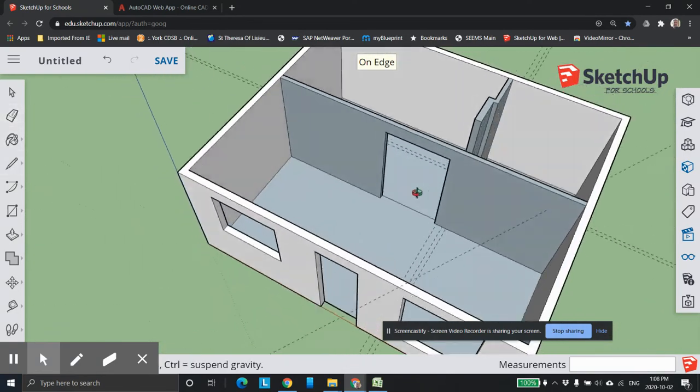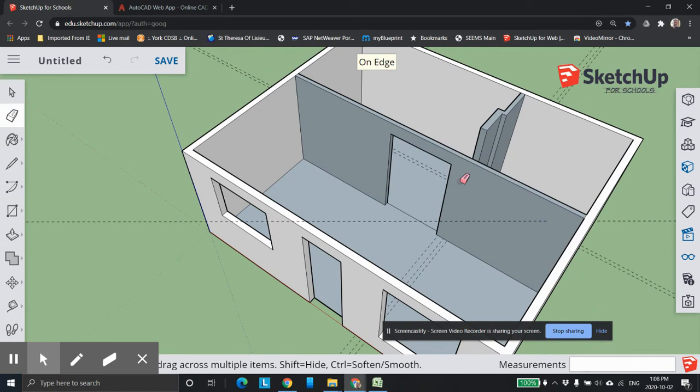All right, so that's the next step. So this video here, recap, you're using AutoCAD to get the dimensions. As I stated, you can bring the image in, but I think this is a much cleaner way to do it. Use the AutoCAD, tab back and forth between the two, draw your exterior walls, make them the proper thickness, which is usually 6 inches thick. Then you bring your interior walls in, lay out all your interior walls, and then we'll cut all of our windows. And then the next video, we'll start bringing stuff in. We'll maybe add the deck on the front and so on. Okay.